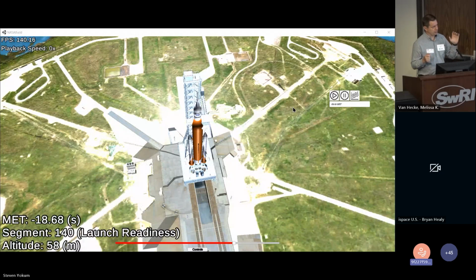That would get boring. So what I did here is pull from the telemetry file. After the SRBs, the solid rocket boosters, separate, Houston is going to command an abort. Something went catastrophically wrong. The launch abort system is going to pull the Orion capsule off, and that's what we're going to watch here. You can see the MET, the mission elapsed time, so that's your negative number. That'll hit 0 at launch and progress. The segment is something that Orion flight software produces, so it moves incrementally through segments as events happen. Those segments are our trigger to do things, to separate things with the vehicle.